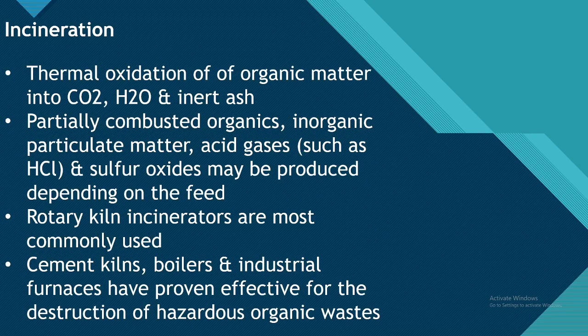Incineration. Thermal oxidation of organic matter into CO2, H2O, and inert ash. Particularly combusted organics. Inorganics, particulate matter, acid gases such as HCl, and sulfur oxides may be produced depending on the feed. Rotary kiln incinerators are most commonly used. Cement kilns, boilers, and industrial furnaces have proven effective for the destruction of hazardous organic waste.